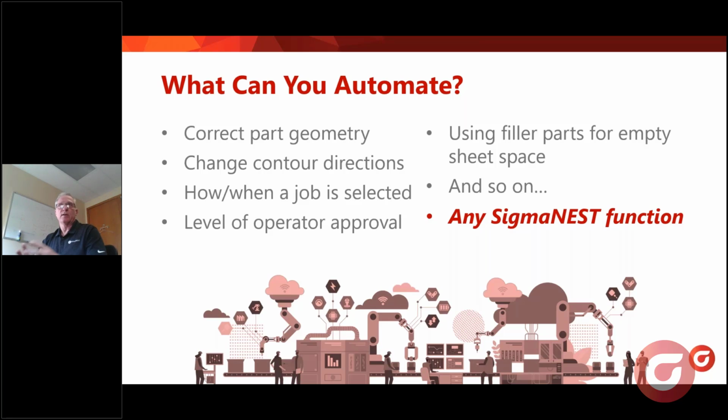Laser is the same thing. You could actually have the thing dictate part size and how that would run part spacings for smaller parts. The other thing too is remnant management. It could be set up so that it nests remnants first by rule, or nests remnants last based on what your preferences are.